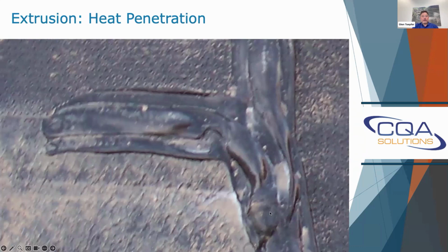And you can see the T weld here. They have to come from different directions. They go one direction to put the weld down, then they come back and either make one pass or in some cases make multiple passes to complete the T. So this area is being reheated several times, and it's already been heated up by the fusion weld, and they trim the lap off to make these T beads. So you're putting it right on top, already reheating that area, and it's a common area for burn through.